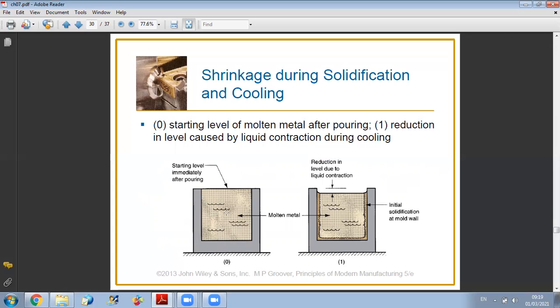Immediately after pouring, due to the difference in temperature between the molten metal and the walls, you will have shrinkage due to temperature difference, because when you cool directly, you have a zone where the density drops very fast, and this will cause a transformation.